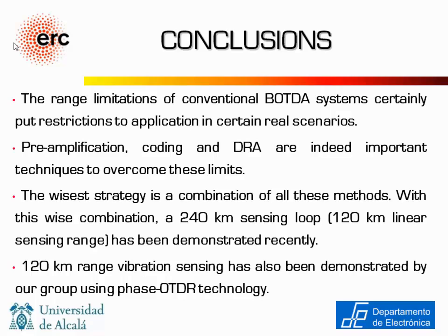Just to show, we have demonstrated this 120 kilometer linear sensing range, because it was in the title. But I couldn't afford it because of time, we have also demonstrated quite recently 120 kilometer range vibration measurements, meaning that you have a linear sensing range of 120 kilometers for sensing vibrations, using phase OTDR technology where you don't have this carryover fiber problem. This is still one interesting thing, and of course I'm open for questions now.